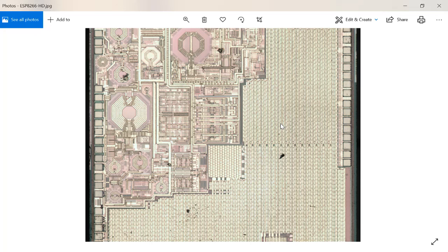So RTL is when you're comparing to behavioral code, the language, right? You can describe hardware in either behavioral or RTL. Behavioral is sometimes not synthesizable. It's just describing, like in a C language, if this, then do this. When this, do this, right?